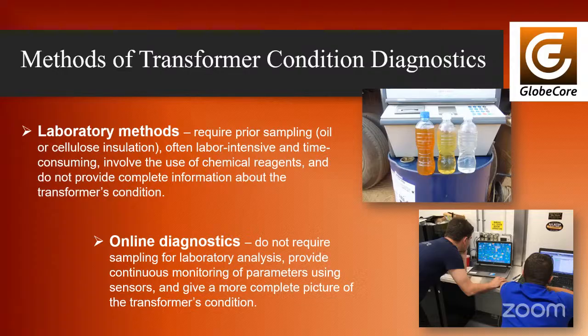That is why online diagnostics are better for reliability. Sensors work all the time, sending data continuously. That helps to detect critical changes in oil and insulation on time.